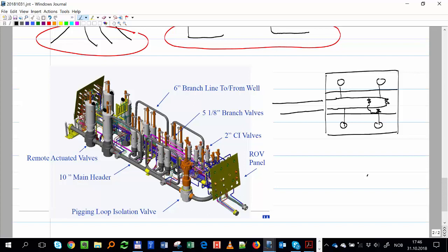Sometimes I want to open the valve and communicate the two headers, and we will see, maybe if we have time, a bit later why we need to have that in place. It's due to hydrates, and we are going to discuss a bit about hydrates today, but let's leave it for later. You have a valve connecting, and here it comes from the well. You have this flexible pipe, and you have two valves, and they connect to these two headers.